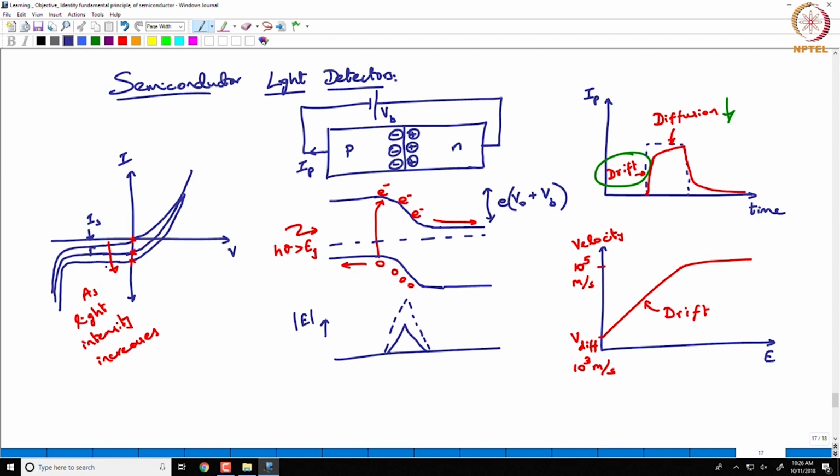Yes, so the question is, can we just review this IP versus time? What we are saying is that illumination is given by this dotted line over here, that corresponds to the power as a function of time, right. You would want an ideal photodiode to have the photocurrent follow that same dotted line, but because only the carriers generated in the depletion region are under the influence of this drift process, the high velocity thing, those are the ones that will come out of the photodiode first.